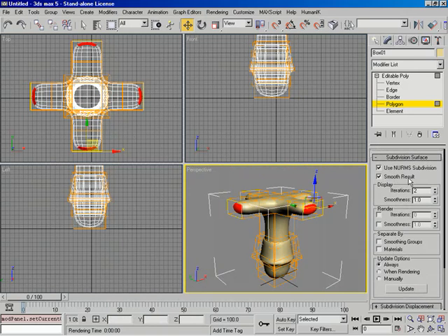First of all, smooth results. What this is going to do is put my final geometry all in the same smoothing group, just so that nothing's faceted, everything's nice and smooth. Next, we've got two groups, a display group and a render group. This is really important when you start dealing with very complex geometry. The display controls the way that you see your high-res geometry in the scene while you're working, and the way that geometry appears when you render it when the render checkbox is not turned on down here.